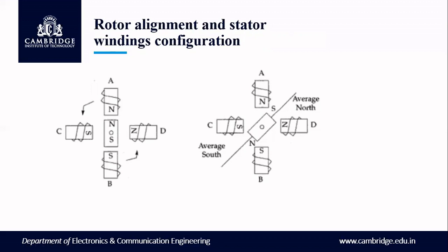The step angle in a particular motor is decided by the number of teeth present on the rotor, that is, the shaft. These rotor teeth are overlapped by the stator teeth. On energizing the stator windings, the rotor will rotate clockwise or anti-clockwise. How you energize these coils A, B, C, D determines whether you achieve a clockwise or anti-clockwise rotation.